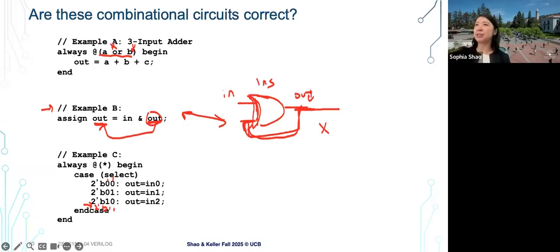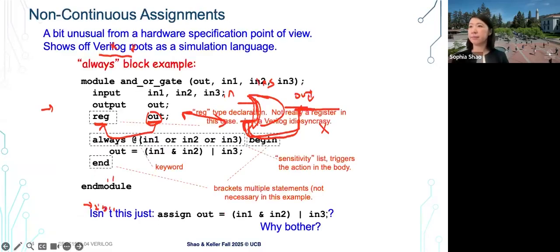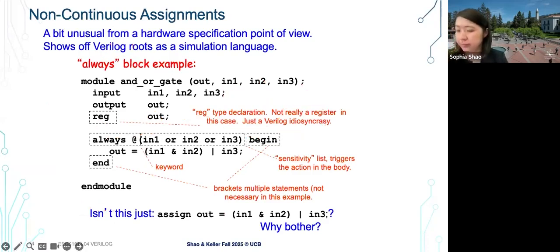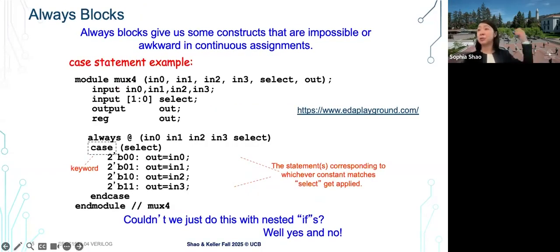Okay, so those are the three examples, but before that, there was a question about the always block. Can you say that question again? Is reg the only distinguishing factor between always and just using raw combinational logic? We'll talk about how the always block is used for sequential logic next, so it's not only for this. Why do we want to use always for combinational logic? For example, the case statement and some operators only exist inside an always statement, not outside it. Those are useful when you think about more complex things.